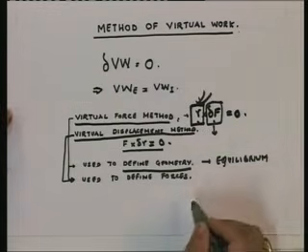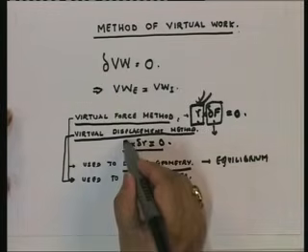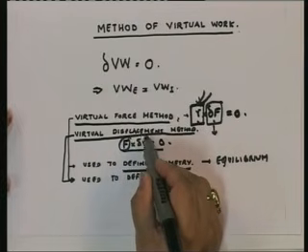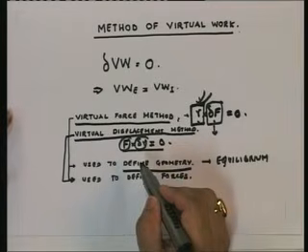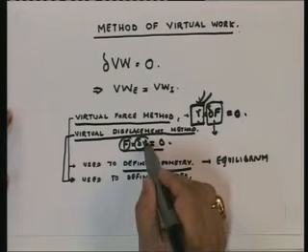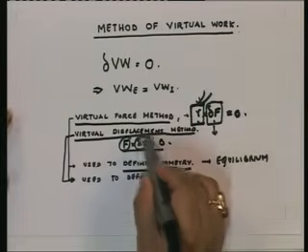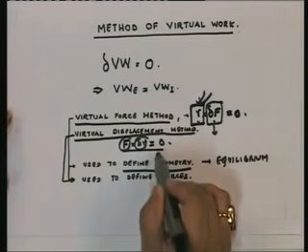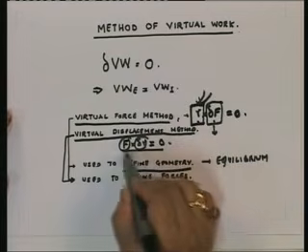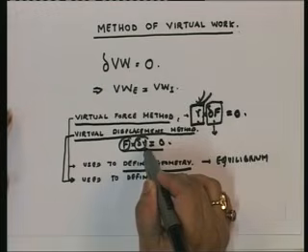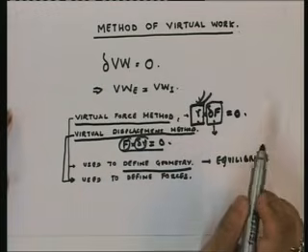to define geometry, and in the next method we want to actually find out the forces by applying displacements. So what do we do? We apply a virtual displacement pattern, find out the displacements and deformation in all the members, and then find out the work done by all the real forces undergoing these virtual displacements and deformations and equate it to 0.